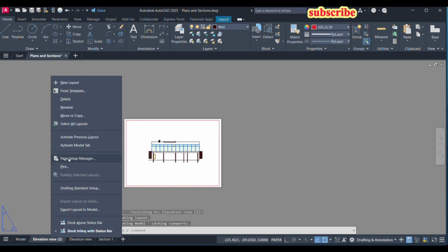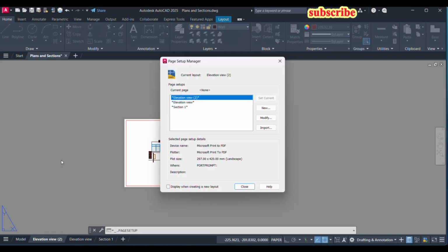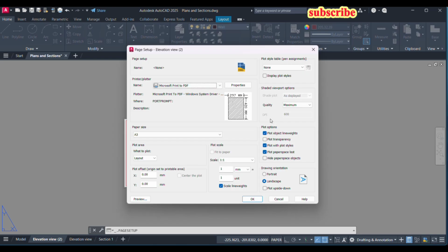Here if you see, we can set up the page, so we can right click on this and click on page setup manager, and here we have elevation view 2. We can modify this to be A3 or A4, depending on what you print. Usually we define this to be A3, and I recommend to you to have a scale of 1/1, which means 1 millimeter equals 1 unit here, because later we can define the scale when we are laying those views in the layout.